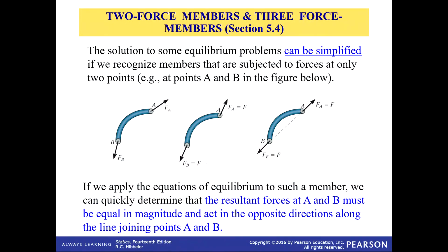One of the other concepts is this two-force member concept. So you can have a force. It's pretty simple when it's a link. This happens to be a bent link in this particular case. So if you look at this bent link, if this link is in equilibrium, then the force on one side has to equal the force on the other side. The lines of action for those two forces are on the same line of action. So a two-force member has the same force on both sides when it's in equilibrium.